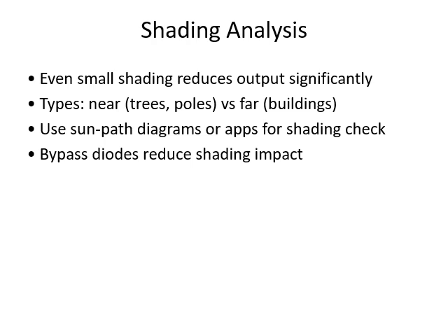Okay, shading is a common phenomenon, but we should not be installing our photovoltaic panel near any place where there is a confirmed chance of shading. That means we should avoid being near trees, poles, or buildings. So all these things we need to carefully check whether they are creating any shade, because even a small area of shaded condition will cause a significant drop in the output voltage and current.